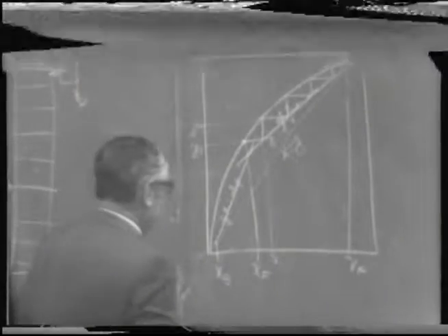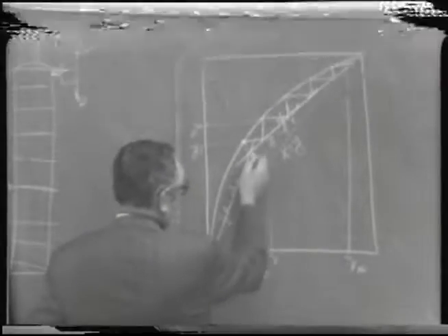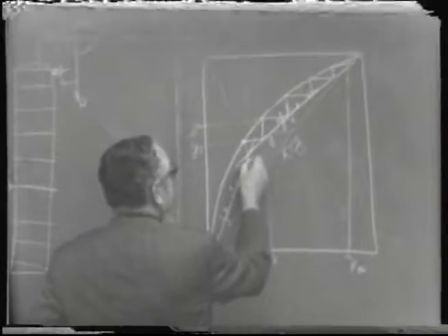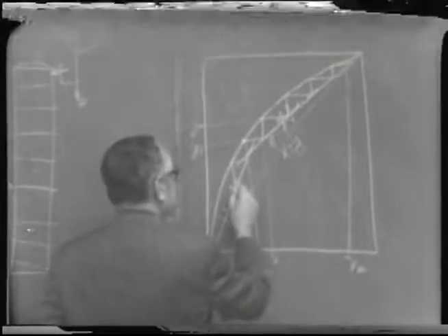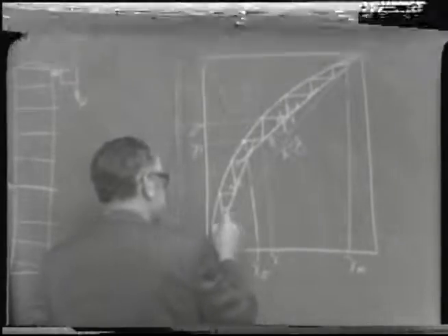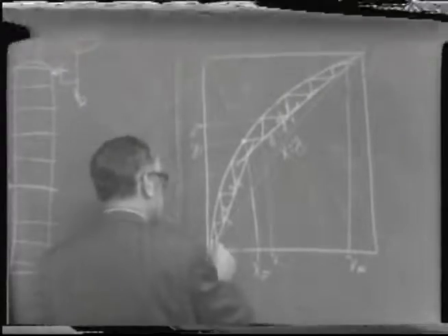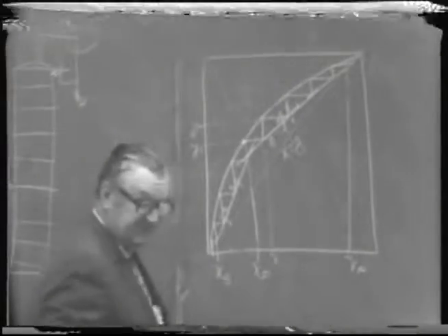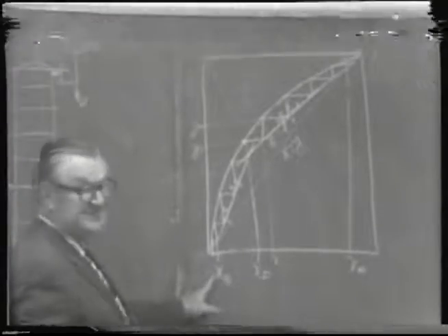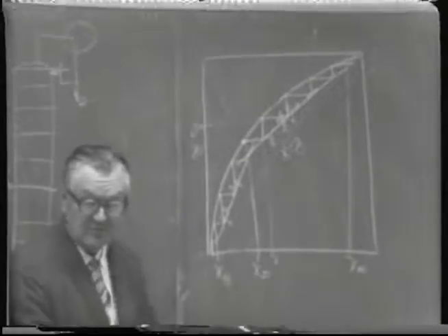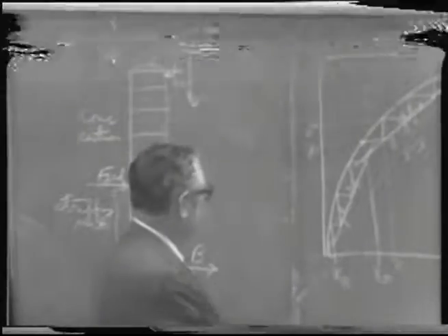And it can be shown that to the left of the point of intersection of these two curves, we'll have steps between the curve and the operating line which indicate the number of steps required to do the stripping, to remove the concentration down to the specified allowable limit in the bottoms product.